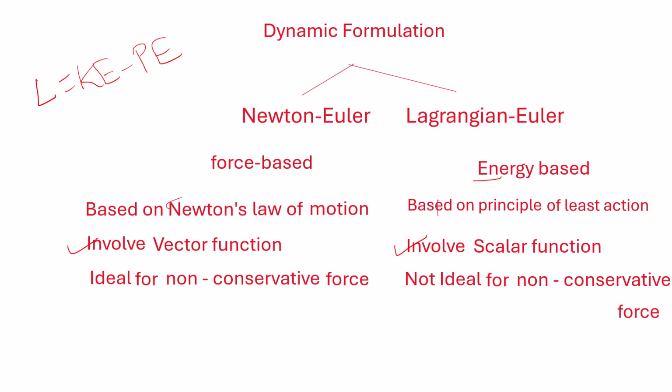Both the Newton-Euler and the Lagrangian-Euler formulations provide a closed form solution, which is computationally intensive for real-time control based on such a dynamic model. I can say it is not impossible, but it is inefficient. The two approaches are inefficient. So in order to improve the computational speed, we also have recursive methods, and approximate models based on simplifying assumptions have also been developed.